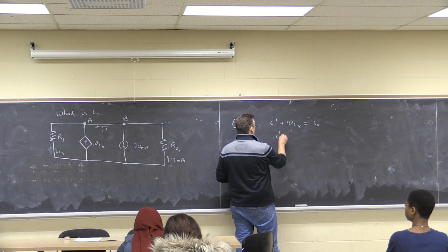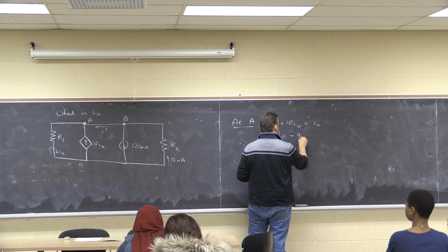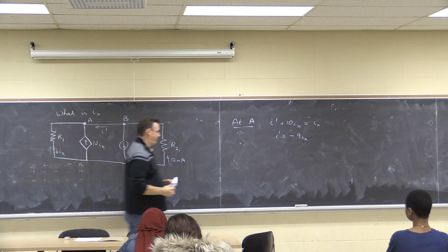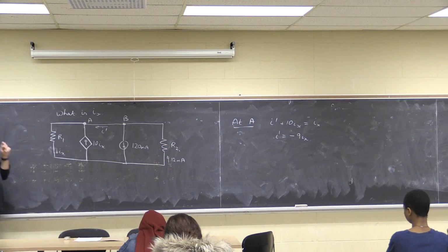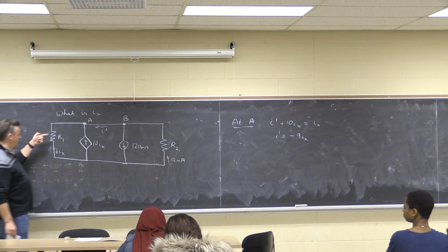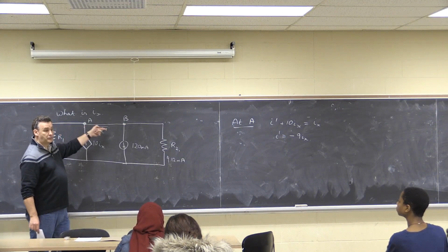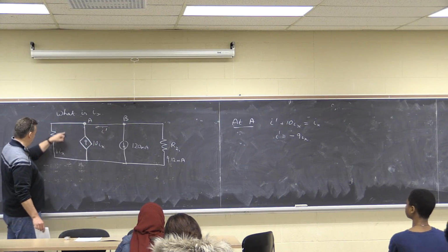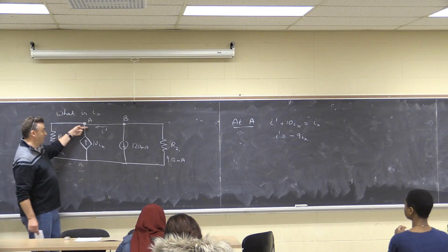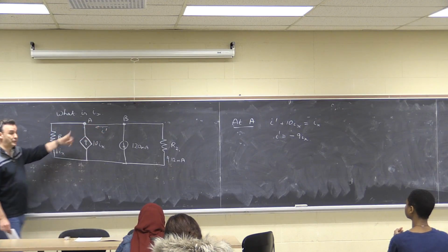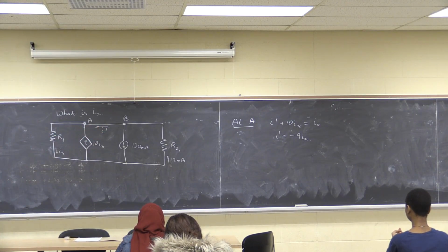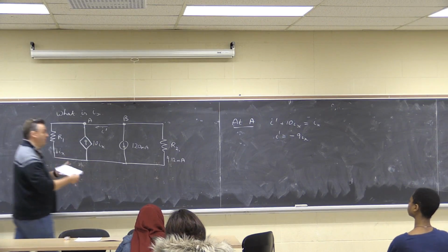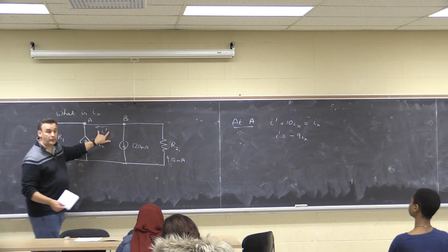So that tells me I prime equals minus 9 IX. The minus sign tells me that the current is really going the other way, and this begins to be obvious, because if I've got 10 IX coming this way, I've got 1 IX coming that way, I must have 9 IX going out in that direction. So as long as you draw a picture and put arrows, when you get a negative, it means the current is going in the opposite direction to how you defined the arrow.